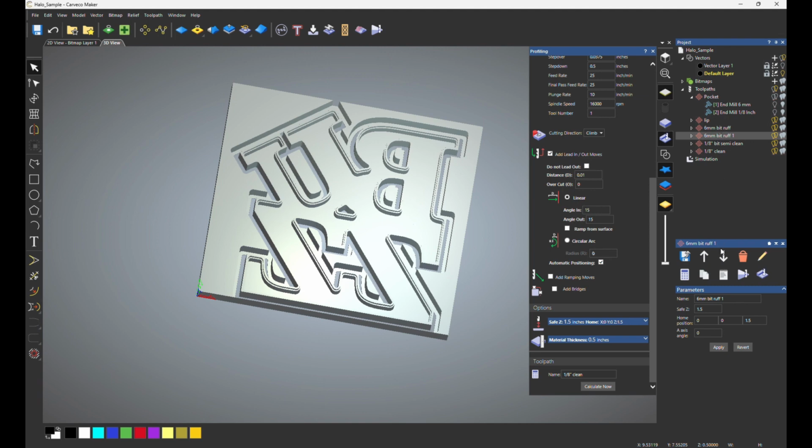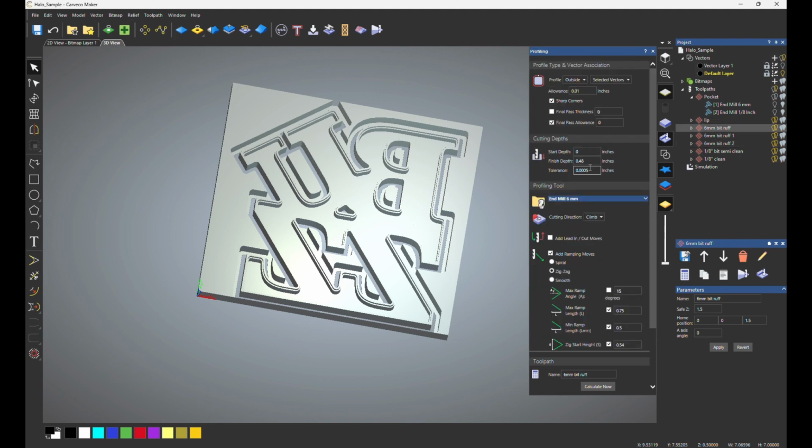You can even do it in 3. Let's do it in 3, just because let's assume that this thing is made and you're doing it with like the Makita router or something. So I'll duplicate it again. The third one will keep the same, so this one would be your normal roughing path. But let's go with this one first. This one we'll start, and we'll make an offset of 0.125. And we're actually only going to go down 0.875, 3/16. Okay, and we'll hit calculate now.